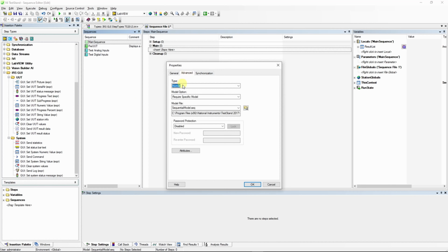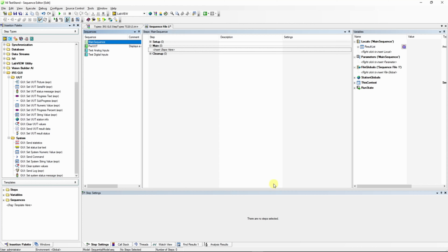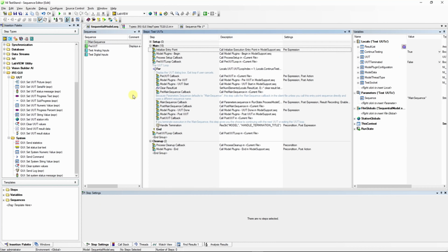Tip 1. Use the process models. If possible, use one of the TestStand default process models or a custom one derived from the standard models. The models send important status information which will be evaluated by TUI.